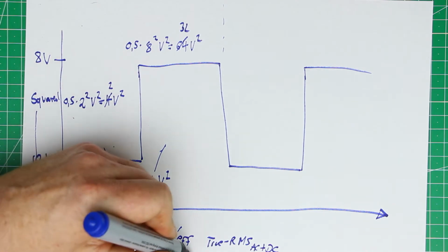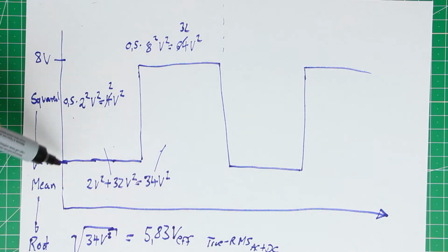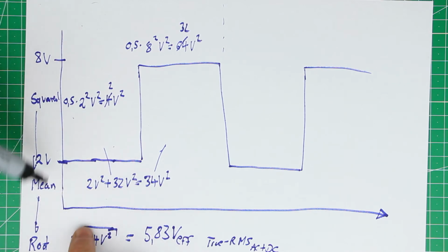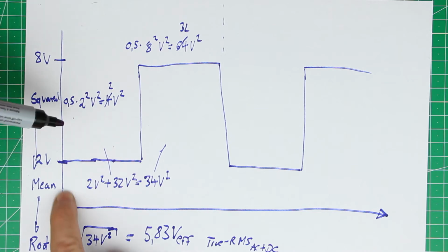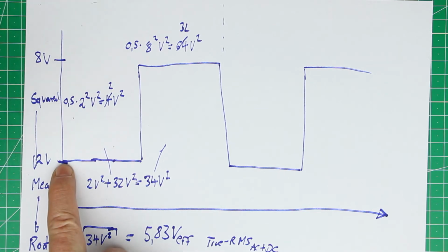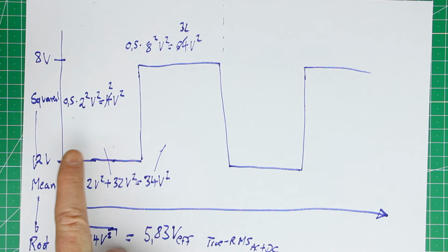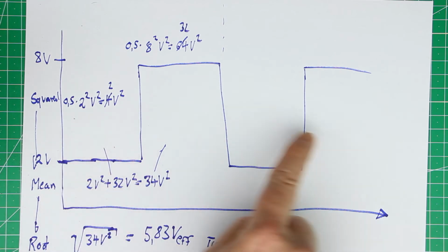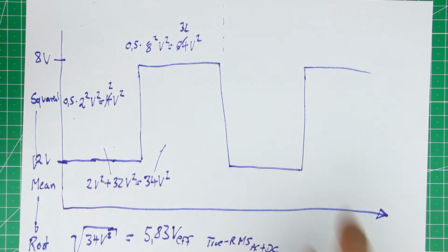We know that this is the correct value, and of course it's very important that your multimeter measures the absolute values, including any DC offsets. Now, what would we get if we simply put a capacitor in front of the multimeter?